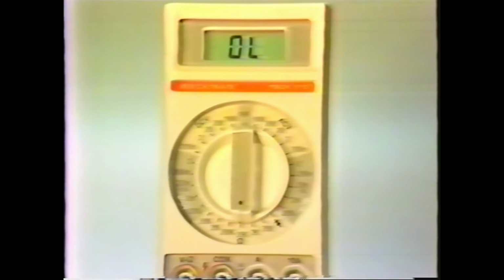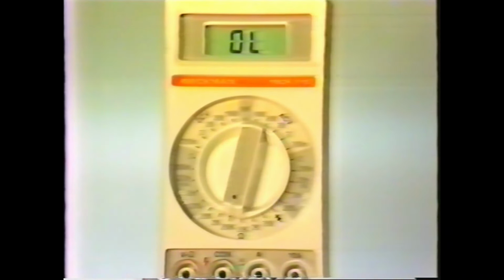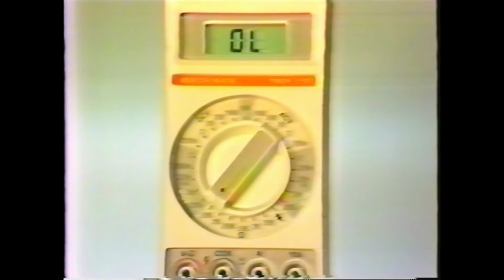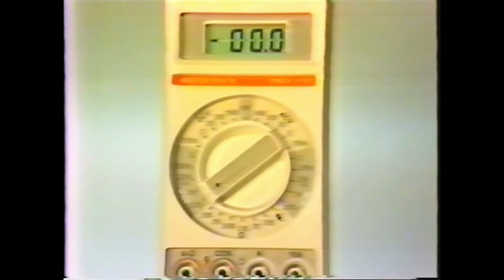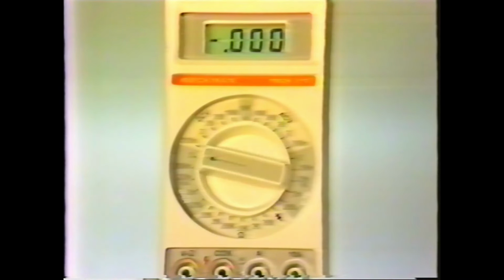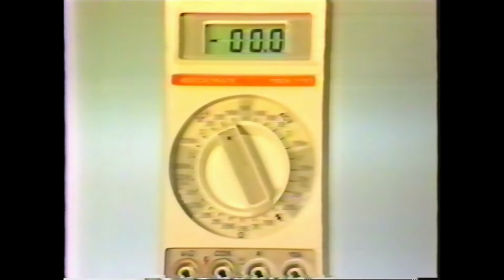The meter can also measure resistances from as little as 1/10 of an ohm up to 20 million ohms. Although the meter has AC and DC current measurement capabilities, we don't measure current when repairing games, so we won't talk about the current settings. The meter also includes a special diode check function that's useful for checking all types of different semiconductors. We'll look at all these tests during this lesson.